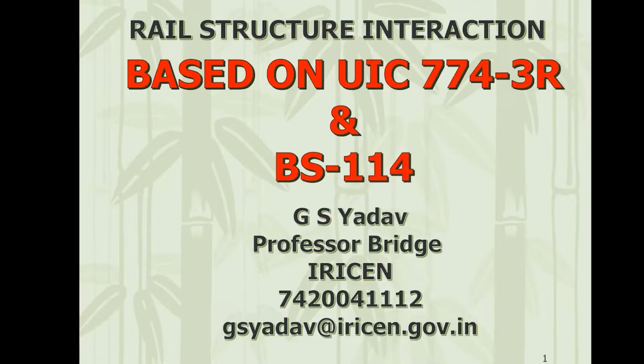For example, for this issue, you have a separate Spanish code, UK code, German code, Korean code, Chinese code, right? They have made their own codes, but the basic document is UIC 774-3R. On Indian Railways, we have not made our separate code. We have simply said that we will follow this, but some of the design parameters that will be applicable to our track, that we have specified in the bridge rules.